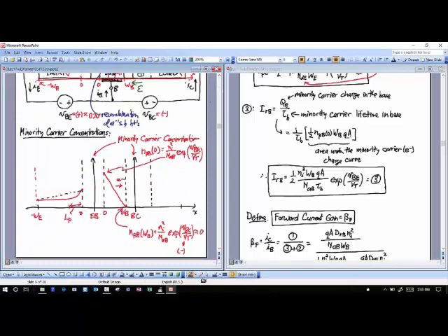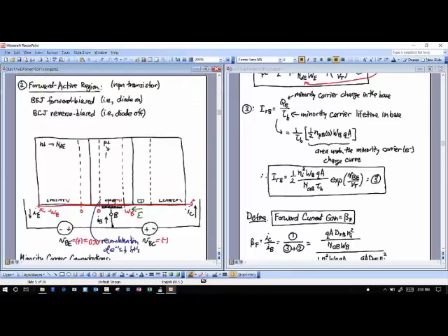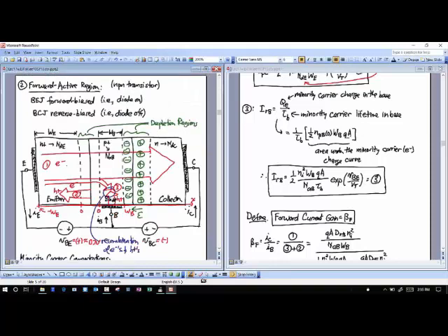So this recombination current has to do with, again, these electrons that are being injected from the emitter to the base. You want them to go all the way across the base and reach the collector, but what actually happens is they recombine with holes in the base. And so if you think of the physics of this, I've got some electrons going through the base. And anytime I have something trying to pass, say this is a big atom right here, I've got an electron trying to pass that atom. So this electron will make a right pass. This one will be influenced by that atom a bit. This one will hit that atom right there. Okay? So you can think of it as a capture cross-section.